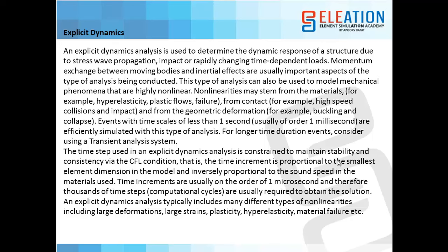It means that whatever time step we give, it depends. If we give a lesser amount of time step to capture the phenomena, it will take more time, because it depends on the size of the element. So if your element size is very small and you also give a very small time step, then the solver time increases drastically. So you have to maintain the relation between them.